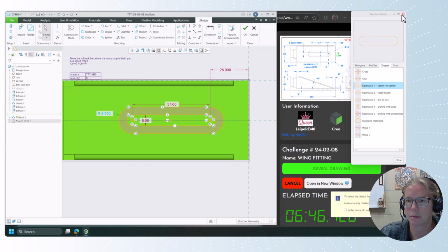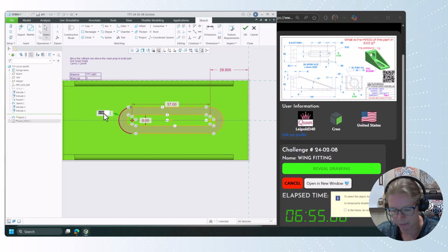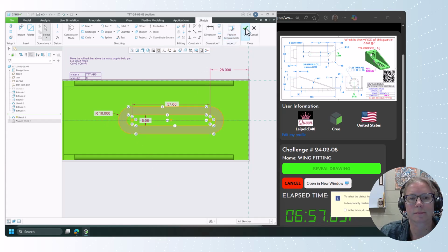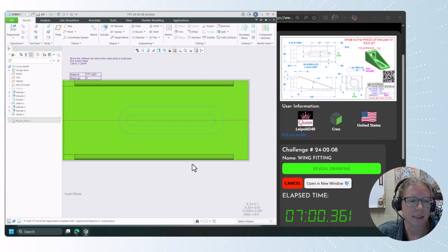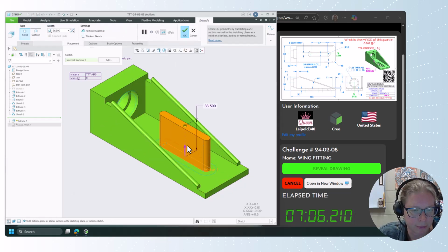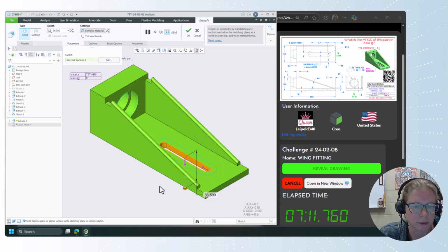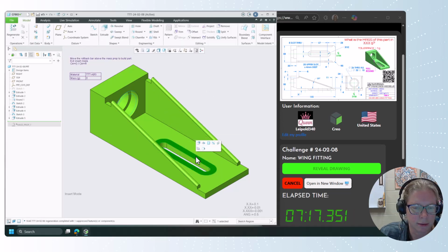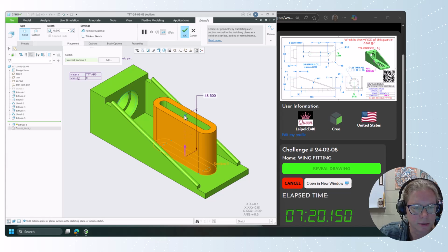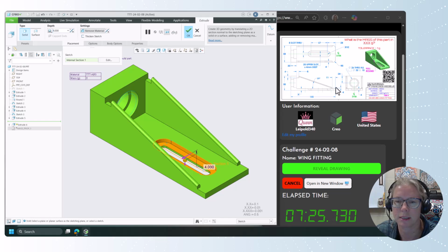Let's close this out. Something's going on here. Oh, I'm still on sketcher geometry. That burns me all the time. I love using the filter. I always forget to unset the filter. All right, Control D. Let's turn off that plane to give me a little better sketch region. I can right click here and do, oh, no, I wasn't. There, do to next. And then extrude. And let's drag this down. And that is going to have a depth of 4, right? And that is shown right here.